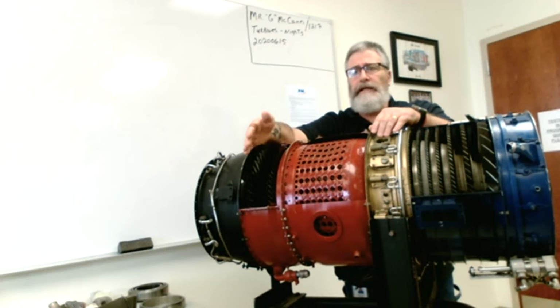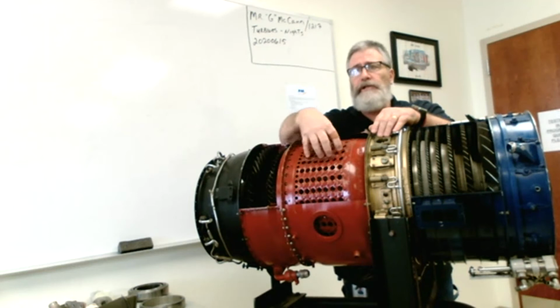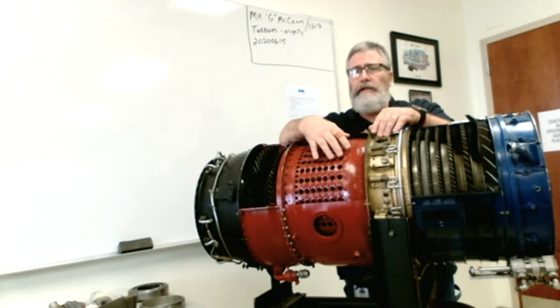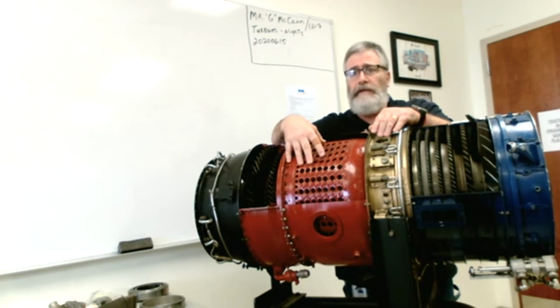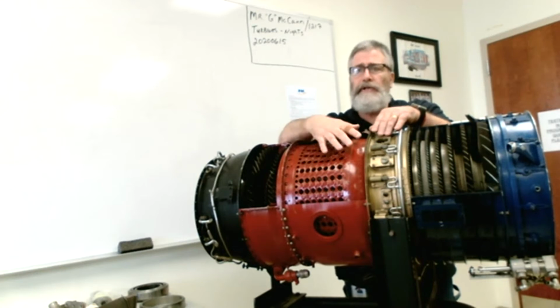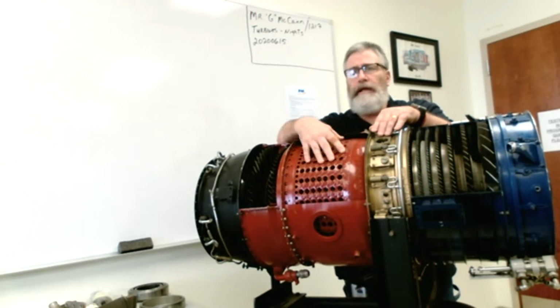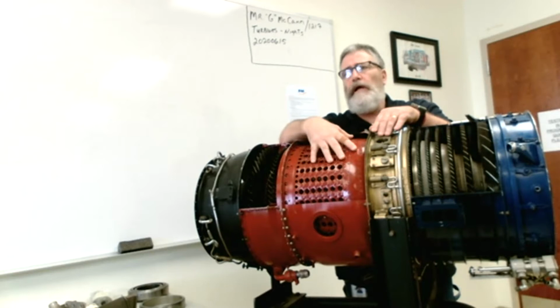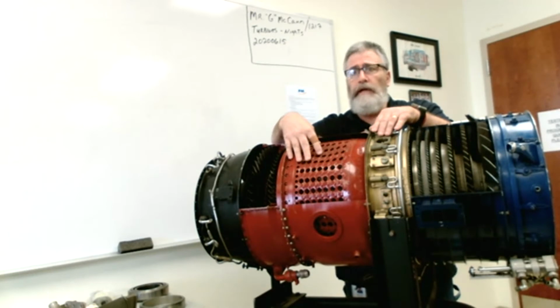The other thing is that it has perforations and louvers, and the idea is that the flame never actually touches this metal due to the technology involved in making these. And so the remaining 80–85%, whatever it is, is used for cooling.